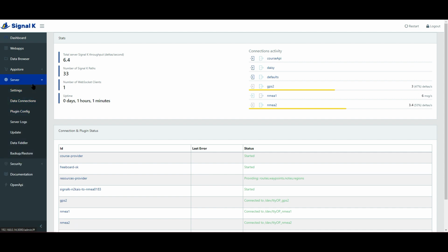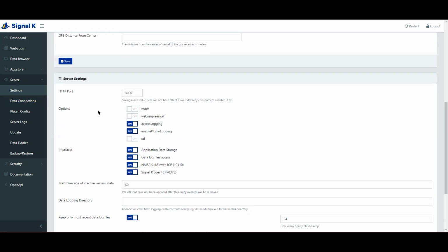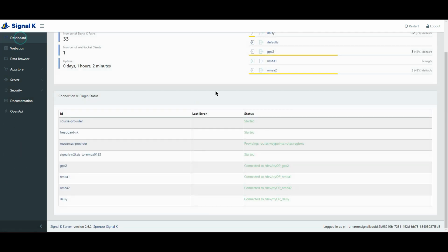So not the Signal K server itself, I am talking about the server for the NMEA 0183 over TCP. On port 10110 there is this NMEA 0183 server. Also, a Signal K server exists if the client understands Signal K data. So on this server, automatically on this port, data is sent which is marked as NMEA 0183 if it's not suppressed. I'll give you the first simple example.